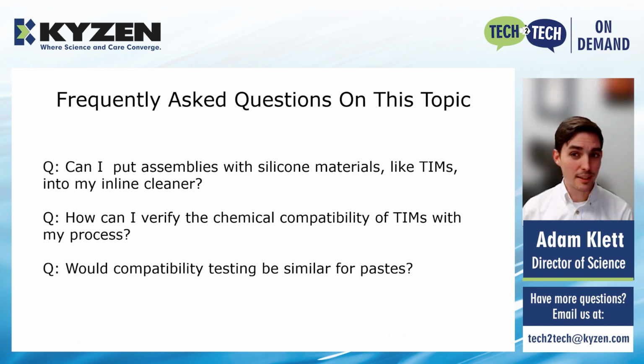All right, so here are a couple frequently asked questions on this topic. The first one is, can I put assemblies with silicone materials like these TIMs into my inline cleaner? Generally, we like to say no unless testing like this has been done, because there are chemistries that will dissolve and extract things out of those TIM materials, and you can end up building that up in your inline cleaner or batch cleaner, whichever it may be, and then that might cause issues down the road for you. And so if you've done these tests and you've qualified and verified that there are no issues, then it's fine. But if not, we highly recommend you to not do that.